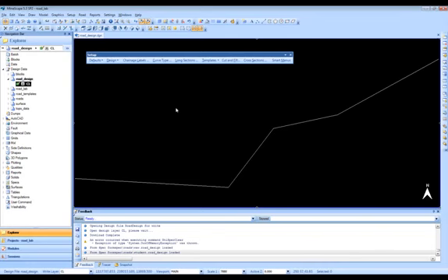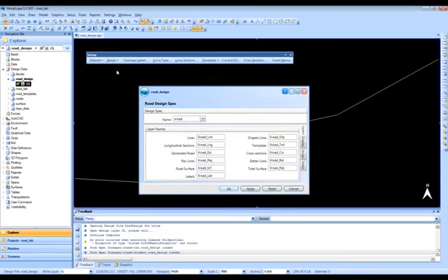Now, another area to set up is the design area. Here we go to design parameters, and these are the parameters wrapped around our road design. So here we give the design file, the road design, a name. I've called it X-Road, and you'll notice when I do that, I get these various layers. These are the layers that will be created, which will contain the various components of our road design.